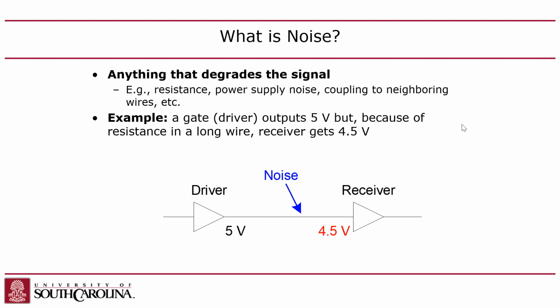It's so bad that if you have a mixed signal chip that combines digital circuits and analog circuits, you have to isolate the analog circuits because they will be affected by that noise. You have to have them on different power supplies, and usually you try to build a little moat around the analog circuits, a little diffusion area around them to block out some of the noise from the rest of the circuit. So digital logic circuits are noisy.